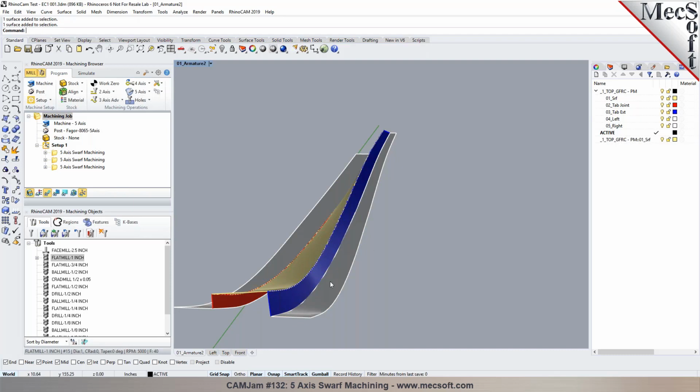Or sometimes, instead of a floor surface, a floor curve might give you a better result. So you have these controls to play with in RhinoCAM. So for swarf cutting, it still reads the ISO curves, correct? Yes, yes. So the surface should be modeled based on the... Yeah, if you have a ruled surface, then it works better for you, right?